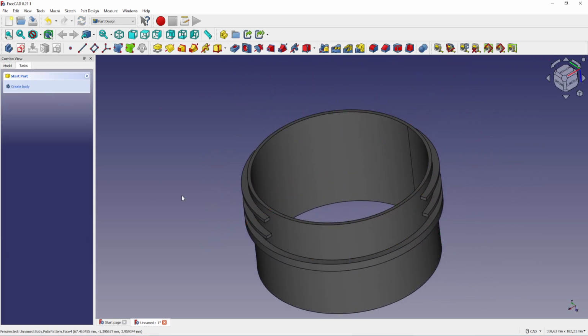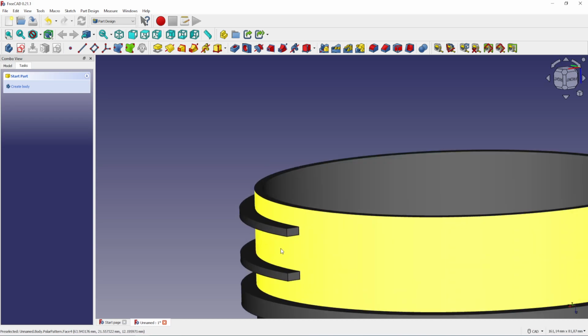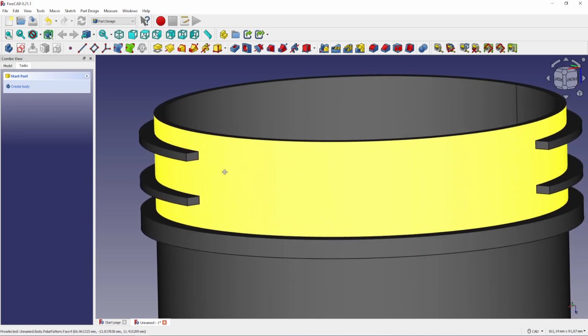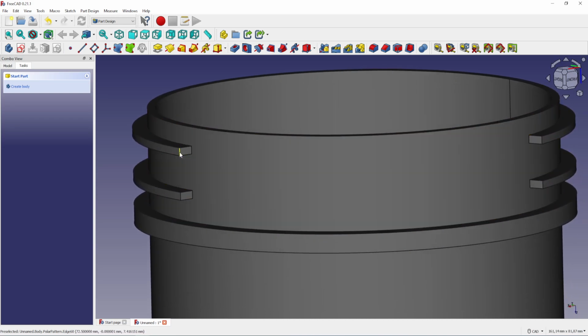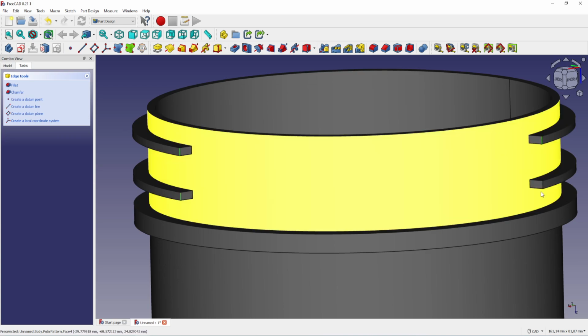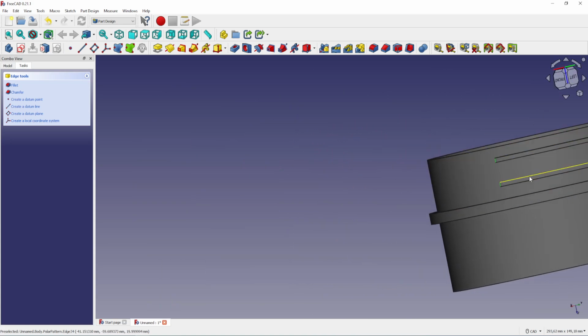Now you can click on OK. The last thing that we can do to replicate the original shape is to add a fillet to the edges. Zoom in, hold the Ctrl key on your keyboard and click to select all of the edges of the ribs.